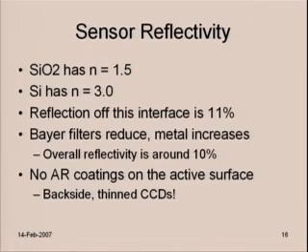Now, for most of the sensors that anyone here could afford, the collection surface through which the light enters the sensor is the active surface of the chip. So you're fabricating transistors on this same surface. The semiconductor people are completely unwilling to allow you to do anything to that surface at all. There's going to be no magnesium fluoride probably in that part of the fab. It's out of bounds. So there is no one that I know of seriously proposing to do any kind of coatings at all on that part of the sensor.